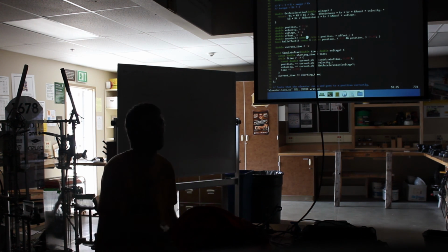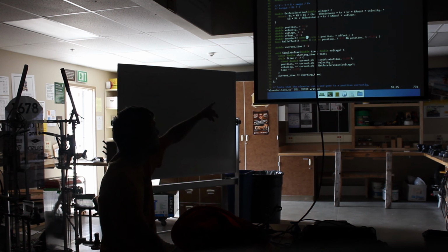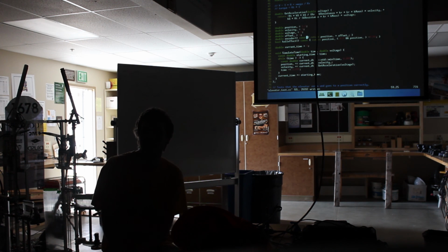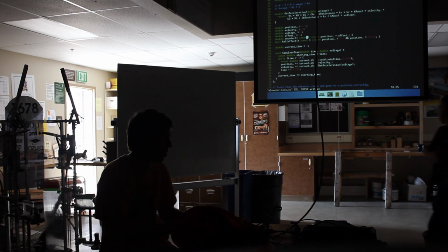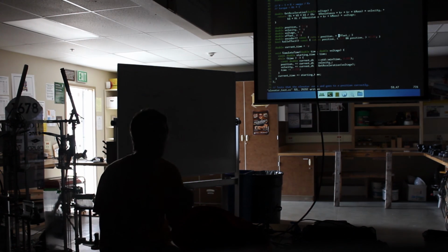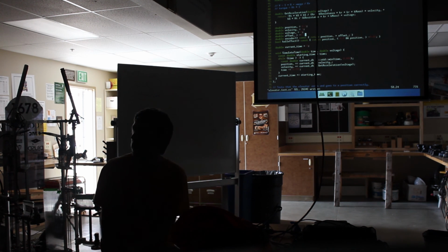Okay, and then if we do that, what is our encoder value going to read when we start? Our encoder value is going to be still 0 in the real world, but here it's going to be 0.1, right? Right, so what do we want to feed our simulation to be more accurate? What do we want the encoder to read when we start this thing? I mean, you could do it right at the start. Okay, so how are we going to do this in our little simulation here? You can see the encoder function here. So if our position starts at 0.1 and we have an offset, we want to add something so the encoder will read 0, so we can set our offset to minus 0.1, right? And now our encoder will read 0, but we'll be at 0.1, so we'll start above it, yet read that we're at 0. So this will test to see if our zeroing code's working.